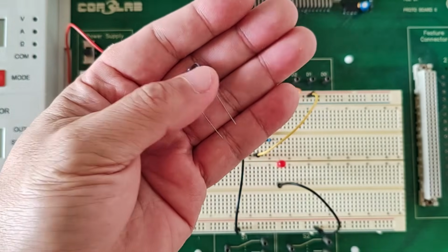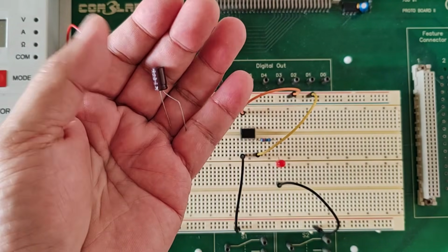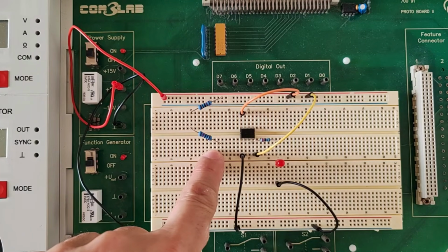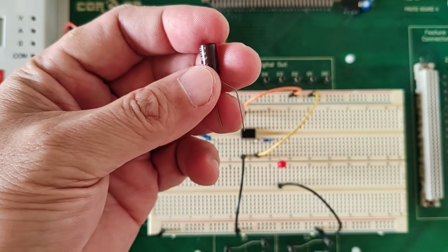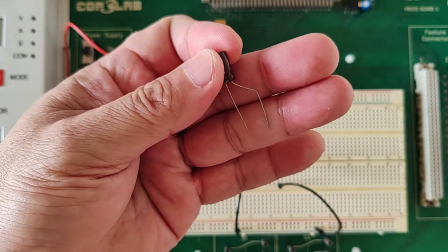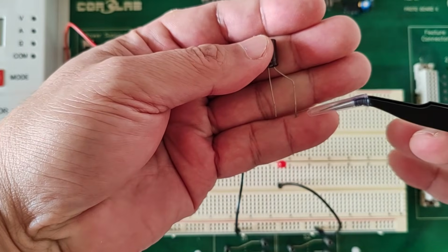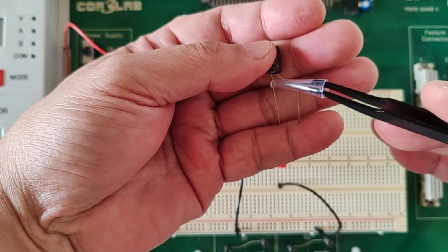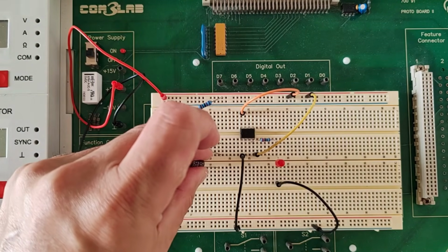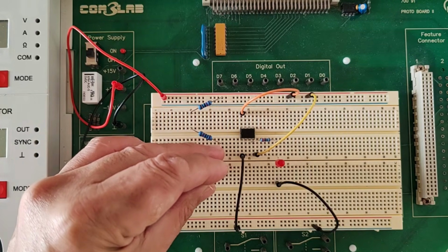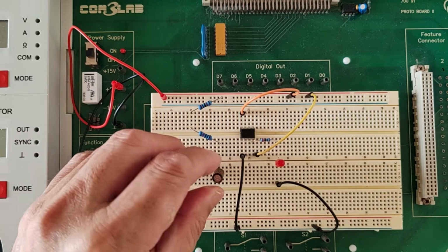Now, the leg of this second resistor will have to be connected to a 100 microfarad capacitor. I have it here. Which leg? Remember, our electrolytic capacitor has a positive and a negative leg. The leg of the second 10 kilo ohm resistor will have to be connected to the positive terminal of our capacitor. That would be the longer leg. It's this one, the longer leg. The negative, the shorter leg of the capacitor, will have to be grounded. Let's do that now. So longer leg connected to the resistor here. Shorter leg on the ground, on the other side, like so.